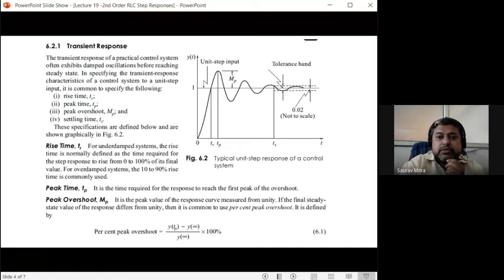So at 0 plus to t is equal to infinity. T is equal to infinity is called as a steady state. So right side, this side, this is called as t is equal to infinity, and initial t is equal to 0, this is called as a initial response. So all this, whatever undulations and all these things you are seeing, it is called as a transient. Okay, so all this undulation, and you are finding this is a damped oscillation, and after that at this time you are finding that ts is given here. After ts you are finding that output has almost become stabilized.